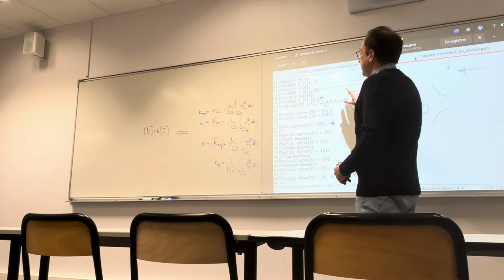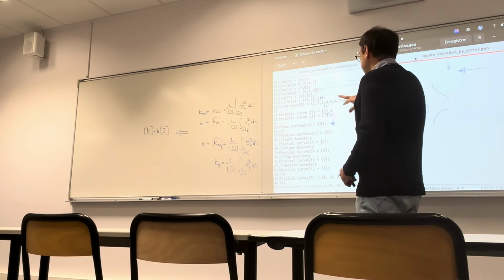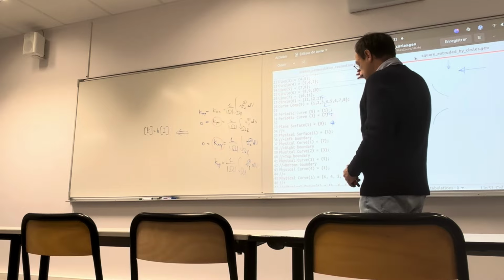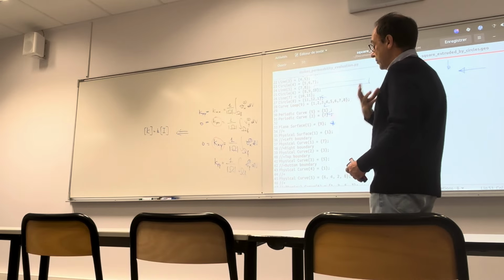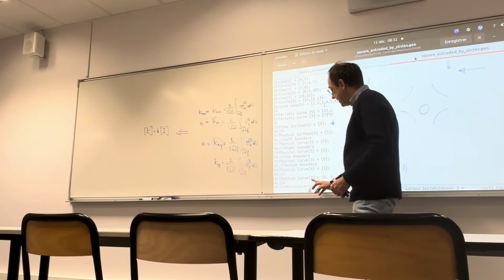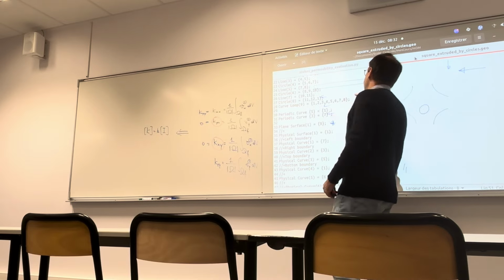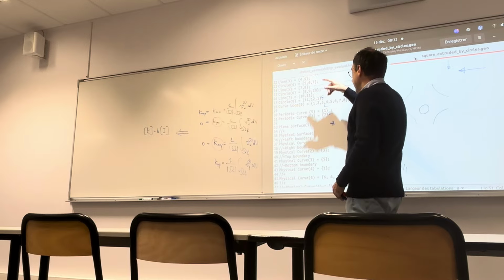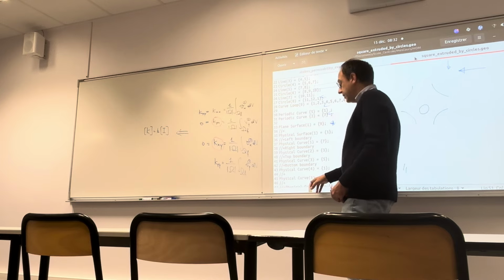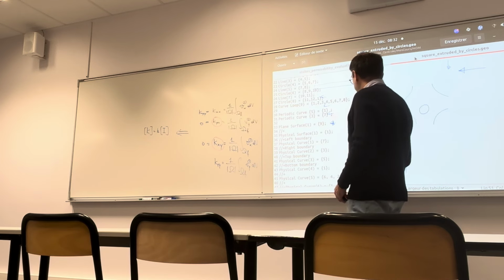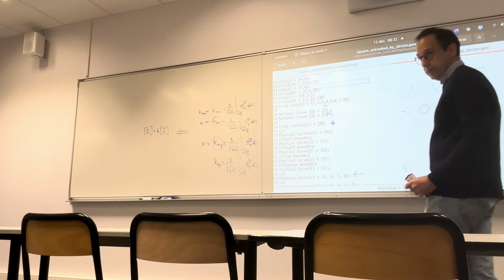You obviously have to add the additional curve. You have to specify that the region is extruded of this circle. The only relation with boundary conditions is the fact that we assigned later, in the PY file, the zero velocity on this physical curve 5. So if you also add the internal circle to this physical curve 5, it's fine. Okay.